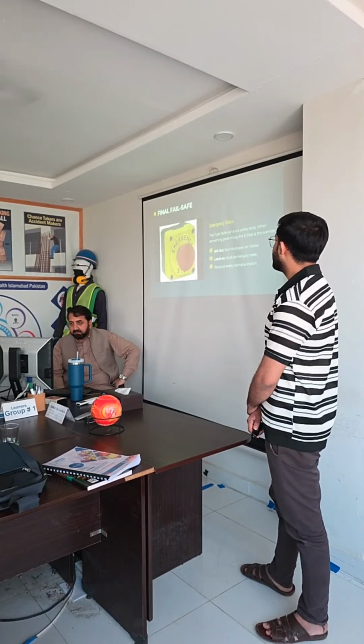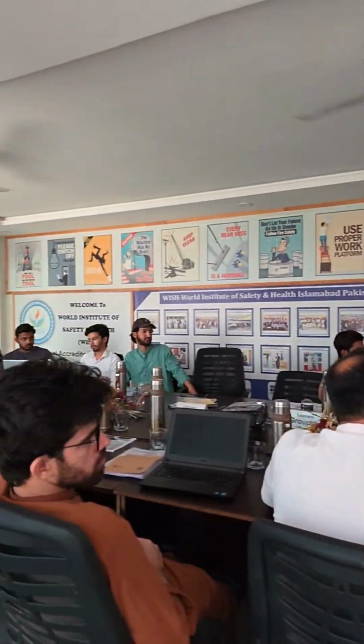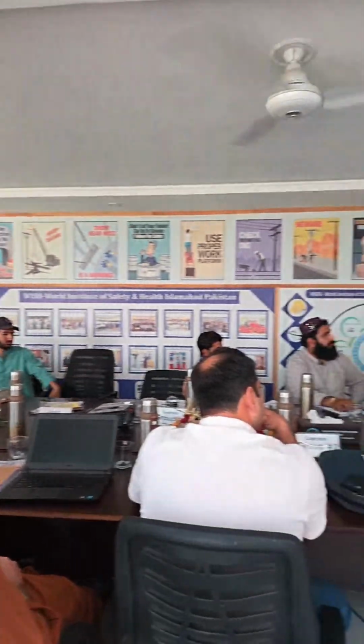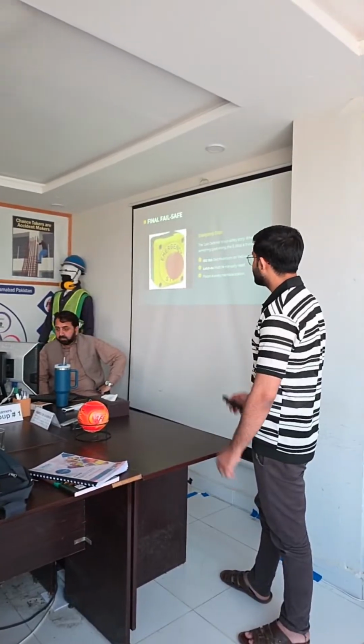Final fail safe: emergency stop. The last defense in our safety story. When something goes wrong, the E-stop is the override. ISO standard: red mushroom on yellow. Latching, must be manually reset, placed at every reachable station.